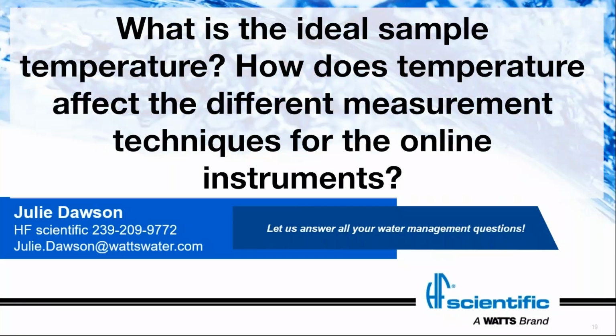So the ideal sample temperature does depend on the technique you're using. For DPD, I think the specifications are between 5 degrees and 45 degrees C. If you are colder than that, you will run the reaction too slowly to react all the chlorine within the reaction time period. So we want to make sure we're at least 5 degrees C for that measurement method.